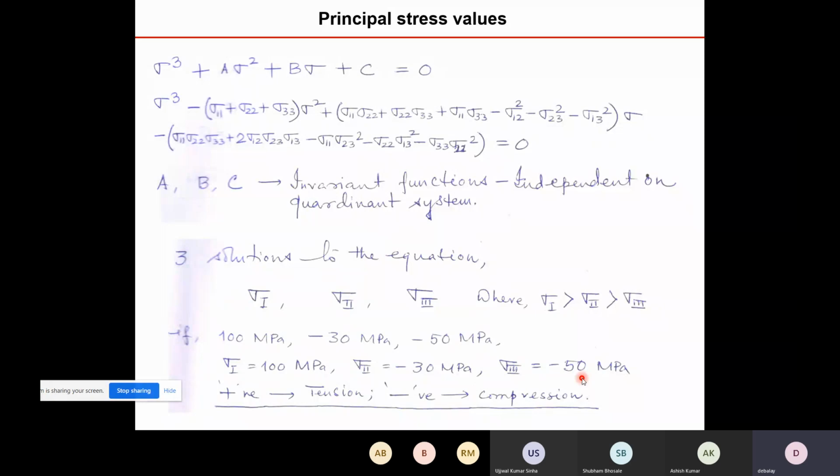For example, in tension, your applied stress is sigma 1, and in the 2 perpendicular directions it is 0. If you are applying stress in the z direction, sigma z is basically sigma 1, and the 2 others are 0. Similarly, in torsion, you rotate the specimen in 2 opposite directions. There we write sigma 1 equal to minus sigma 3 and sigma 2 equal to 0.